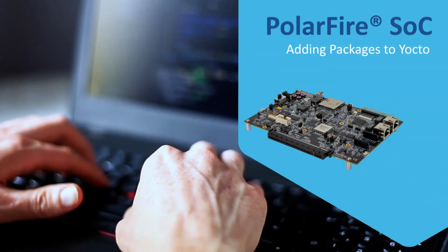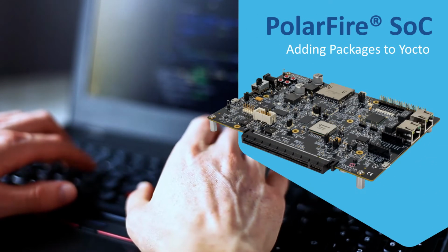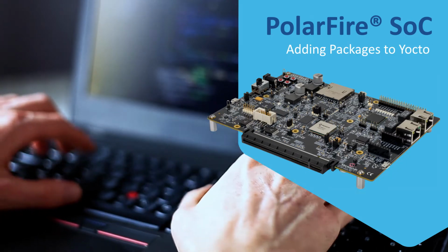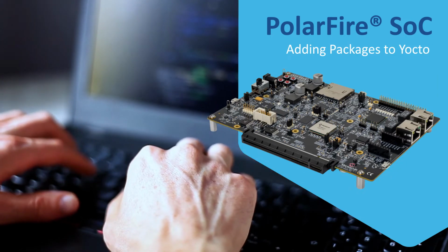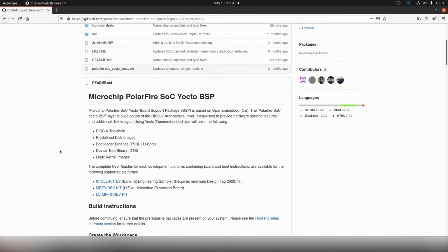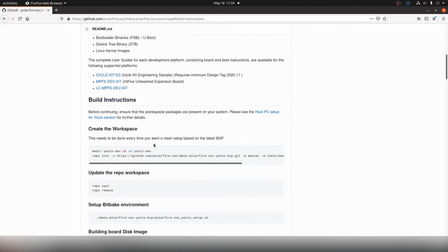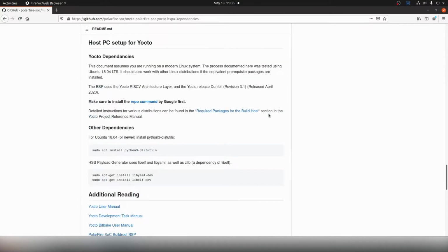In this video, we'll generate a standard Yocto development image for the PolarFire SoC Icicle kit, program it to the board, and test it. To do this, we're going to follow the steps in the README of the Yocto BSP repository.